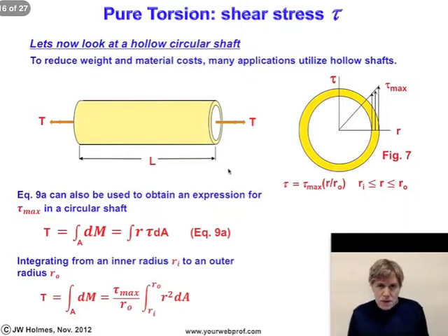Of course, not all shafts are going to be hollow, because it's sometimes difficult to produce a hollow shaft out of a particular material and the size you may need. For simple applications like electric motors, or a shaft in an oil pump, you might just find a standard diameter low carbon steel and utilize that.